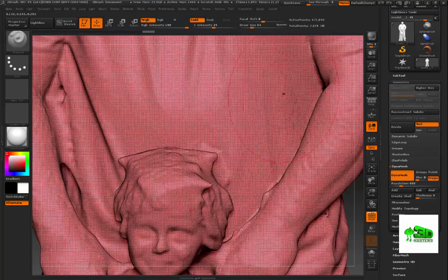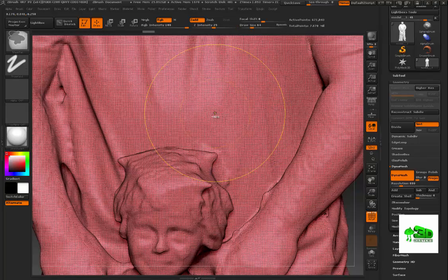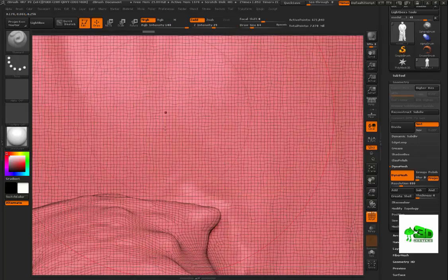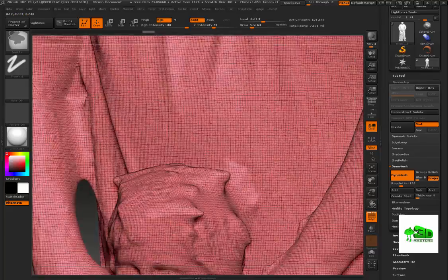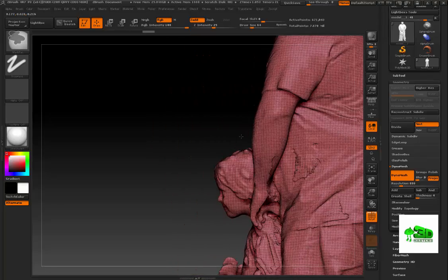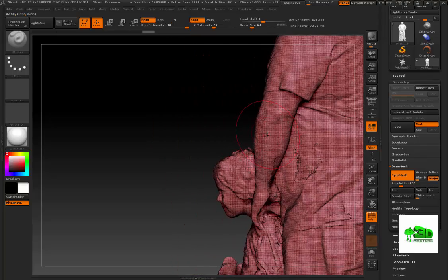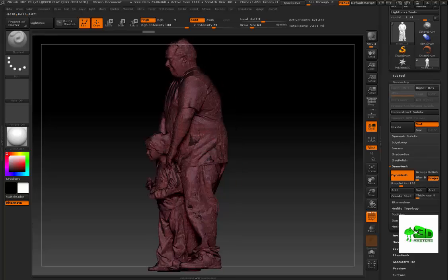And we're done. Now you notice that the polys are all uniform. That's really what I want you to see in this. If you zoom up on it, you can see that they're all set up. It's no longer all those n-gons. It's actually nicely triangulated or quads going around on it, which is really nice. This also makes it so that you can repair this model a lot easier.